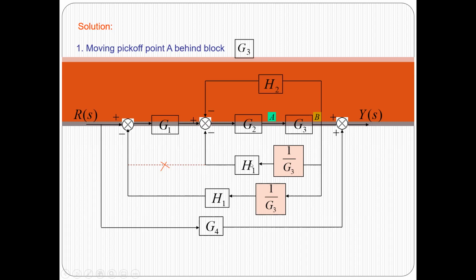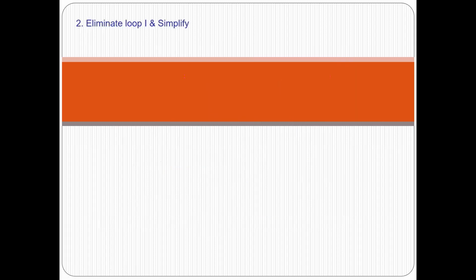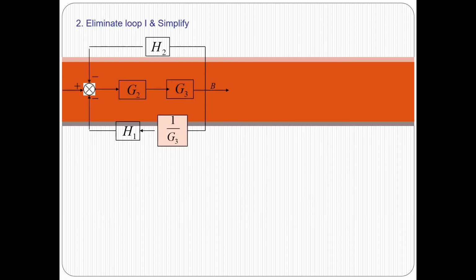Okay. So now these two are in cascade, you can group. These two are in cascade, you can group. And this and this are two parallel paths, you have to simplify that. And finally, you will get one single loop that you have to simplify. Okay, so I'll call this a purple square, the first section, which we have to simplify. I have taken that section separately here.